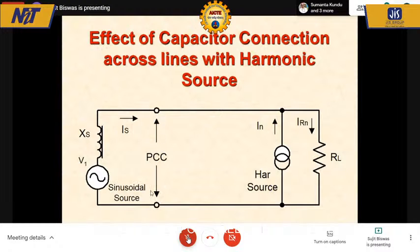This is my point of common coupling, PCC. This is the source current, IS. I have connected some harmonic source on my side onto this point. This is a non-sinusoidal current, let's say a nonlinear load, which is drawing fundamental current as well as injecting harmonic current backward. This is just a resistive load across the line. So this lot of harmonic currents that is created here will try to flow back to the source. It will distort the PCC voltage, such that the resistance will start drawing harmonic currents also.